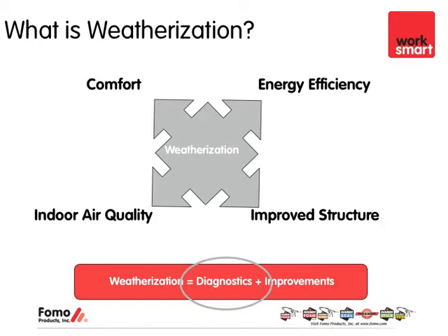And on this one, what we're really talking about is the ability to keep the air inside your house more pure. Mold is typically a byproduct of air leakage, and mold obviously has a negative impact on indoor air quality. So by air sealing, you prevent a lot of hot, moist air from coming into the house or condensing within the housing structure. As a result, you're making the air inside that facility higher quality.